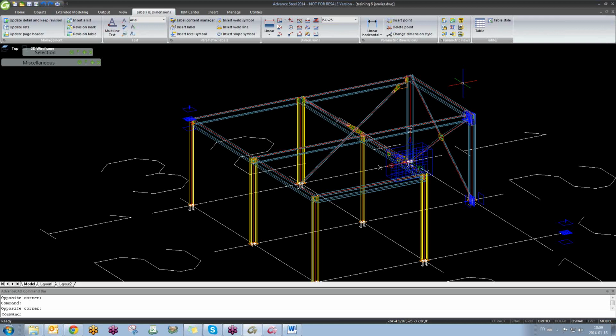Then I'm going to have a roof framing plan, because I'm going to show those beams that you have there as a roof. That'll be maybe sheet E1 or E100, depending on the customer numbering system. Then I may make a sheet E2 and put all the sections that pertain to this on sheet E2. So when I cut all my sections, I'm going to paste them all on sheet E2, and then of course I've got to say section 1 on E2, section 2 on E2, and so forth.